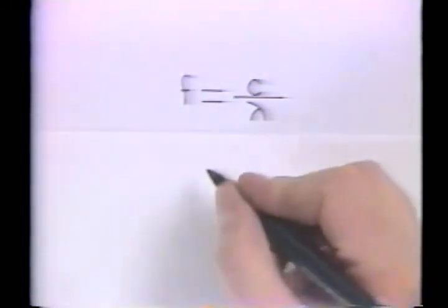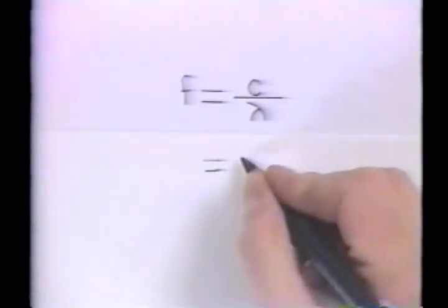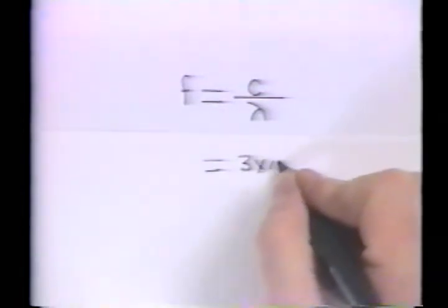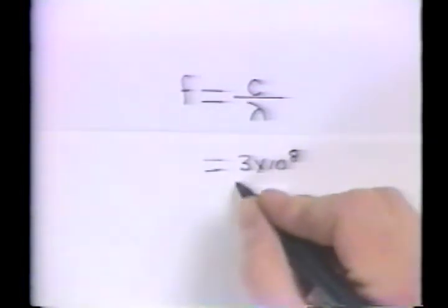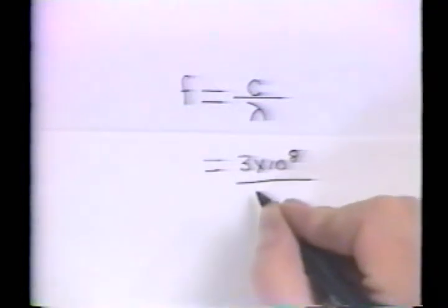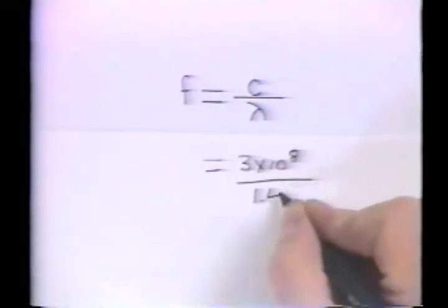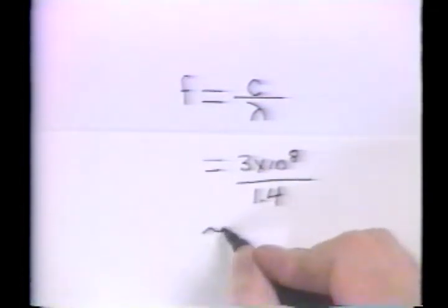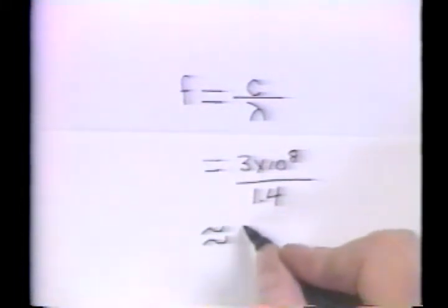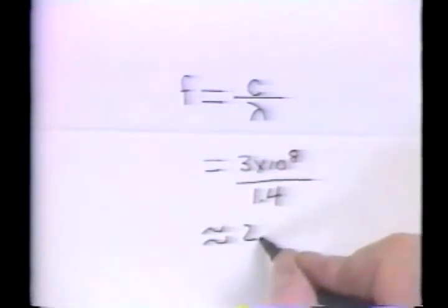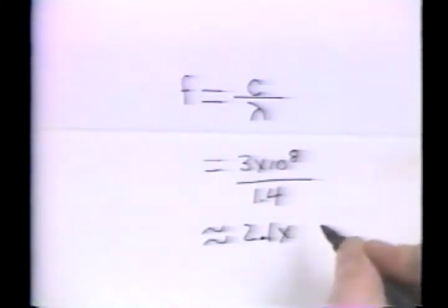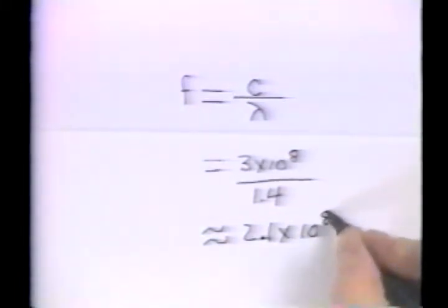This is the frequency that we should deduce from the oscilloscope trace for the magnetic probe. The period is about 5.2 nanoseconds. The frequency is about 195 megahertz. The agreement with the 210 megahertz we found from the wavelength is consistent with the accuracy of our measurements.